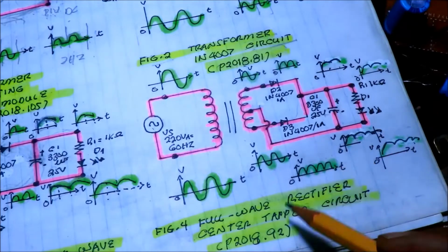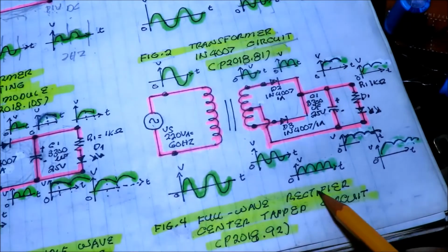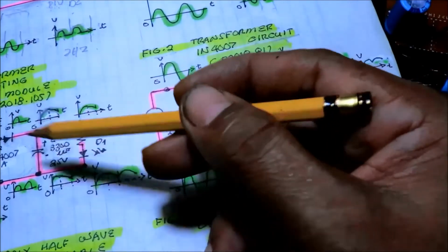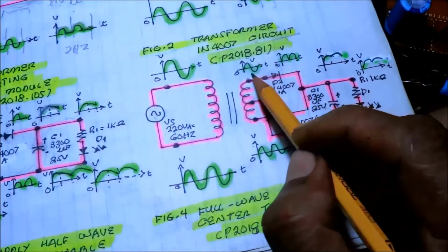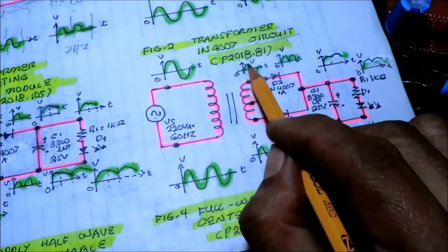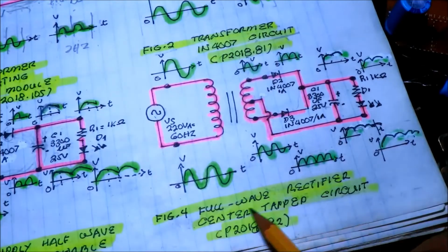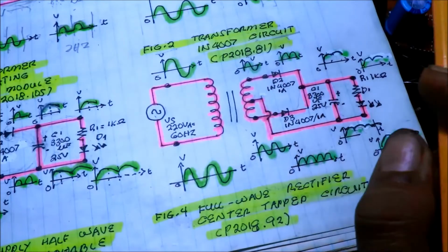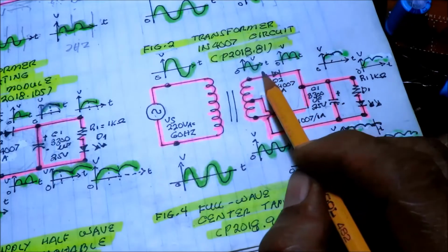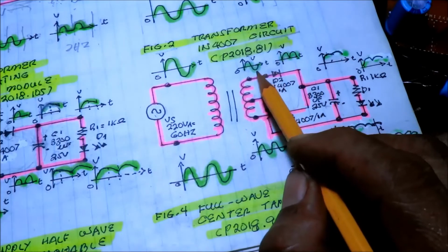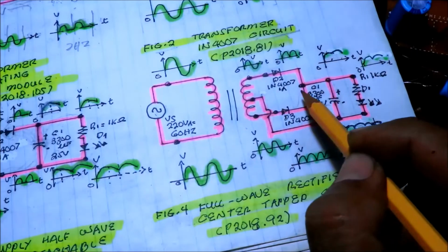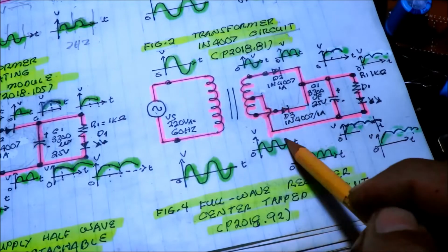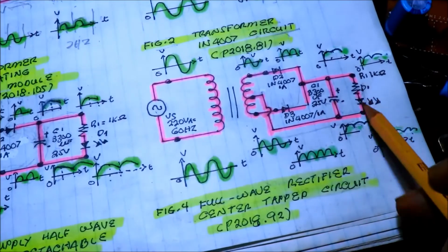This is now another circuit, the full wave rectifier center tap circuit, which is the modification of this half wave. We're now going to utilize a full wave. That's what they call a full wave rectifier. We're going to rectify a signal with good efficiency. So again, I have the two diodes here. That is the construction. I'm using the center tap transformer, the capacitor, and the load.